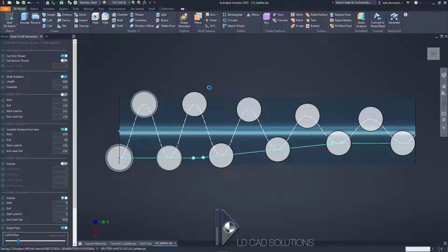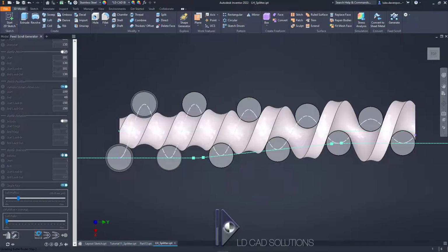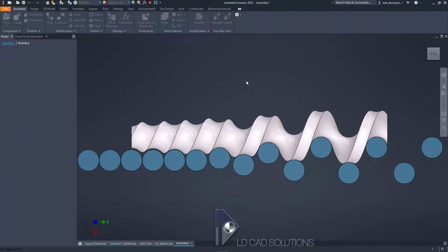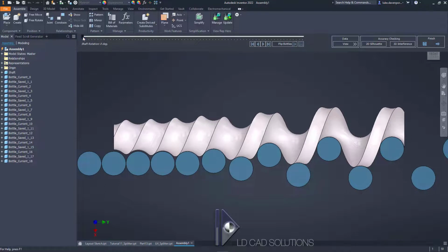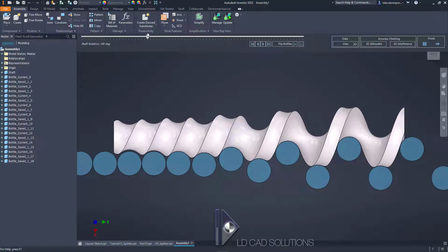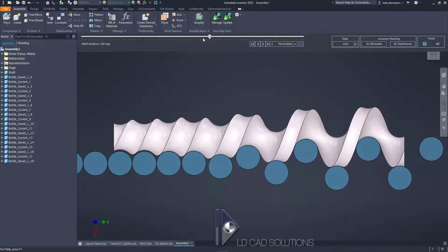So we'll just save this shaft first, and then if we run a simulation of this one down here, then we'll have the option to add the right hand splitter part to the same simulation. Okay, so here's this one. Let's just double check that this is doing what we expect, which it is. You can see the soft entry clearance that we added, that we kept the same here for this part. And here's where we can just add the second shaft to the simulation here.